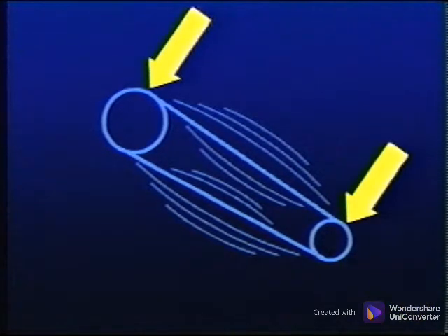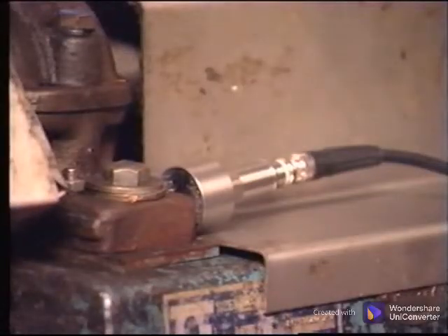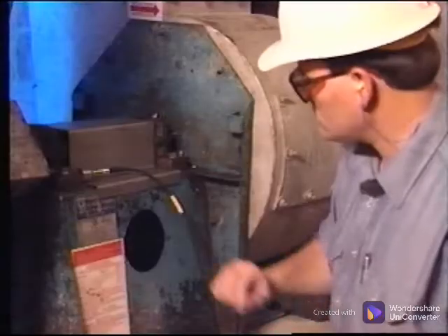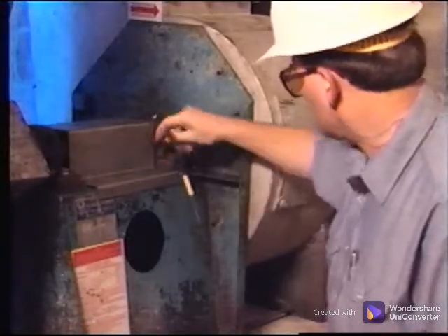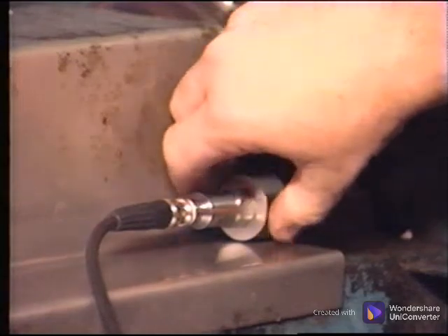The perpendicular or 90-degree measurement better determines sheave misalignment and belt resonance. It is important to acquire good axial measurements to confirm misaligned or bent sheaves. The same recommendations should be followed for these axial measurements as axial measurements on any other machine.